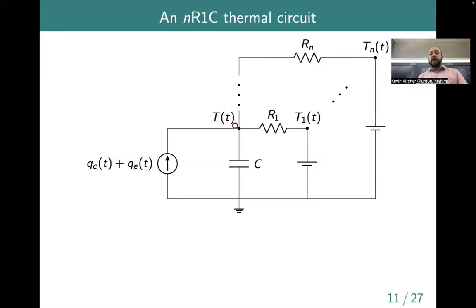We could think of this as the indoor temperature in this room, which is roughly what the wall thermostat is measuring. Then maybe T1 is the temperature out in the hallway. So this R1 would represent the resistance, or the thermal conductivity, of the cinder block that makes up that wall. But it might also have to do with air leaking under the door over there. If I prop that door open, you could imagine that this resistance would change. It would decrease because the rooms would become more tightly coupled, if that makes sense.